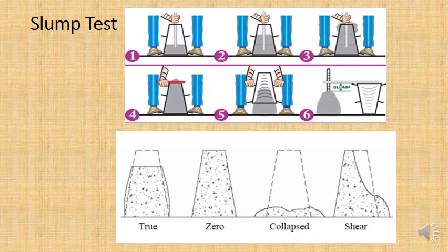Now, if it's a good slump, it's going to be similar to the slumps on the left there. The one second from the left, that's a 0 slump. Unless we're using the concrete as a brick mortar, we need the concrete to be runnier than that. We need it more workable. But if it collapses and it forms a big puddle, that's where you're having segregation. And that means you're going to have a very weak concrete. It still needs to be able to hold its shape.